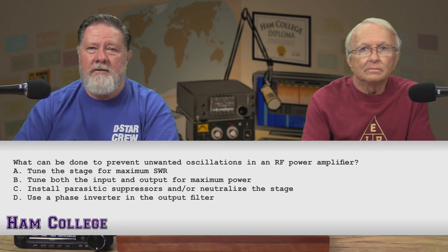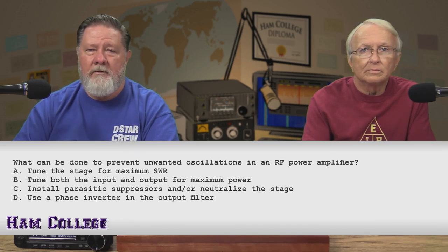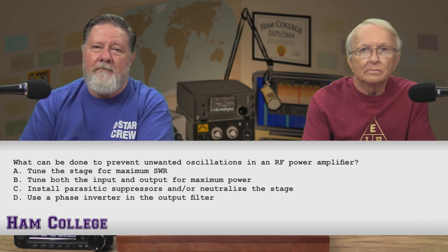I don't think that's it either. C, install parasitic suppressors and/or neutralize the stage. That seems plausible. D, use a phase inverter in the output filter. I'm going with C on this one.